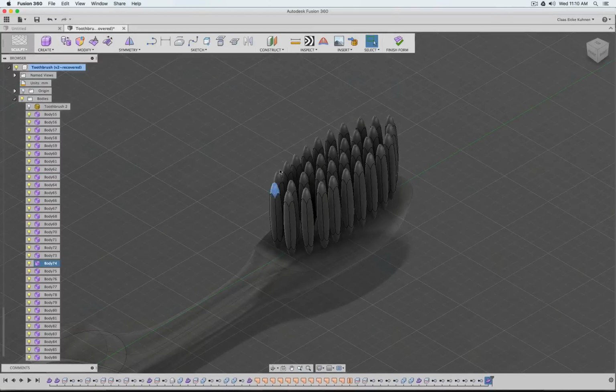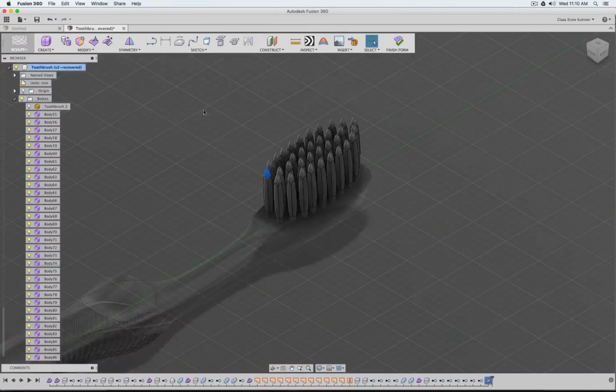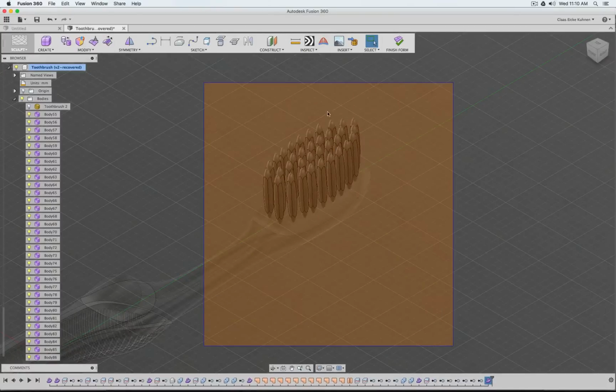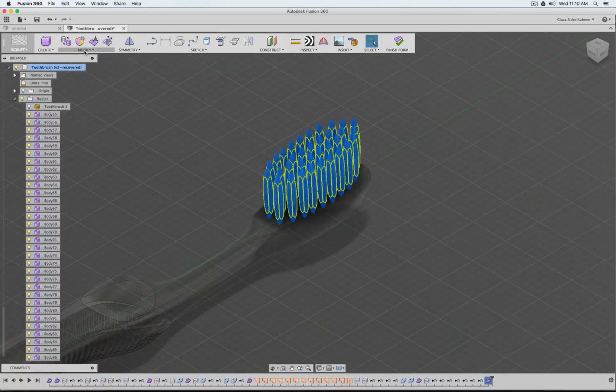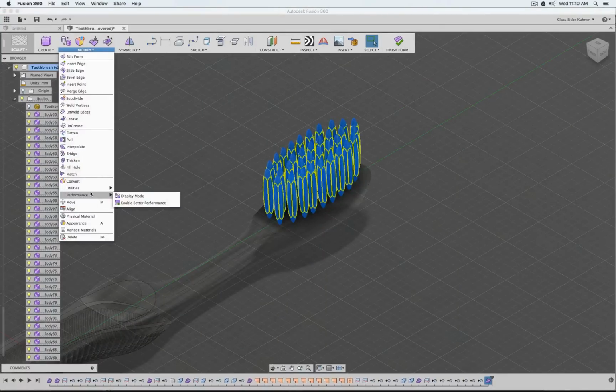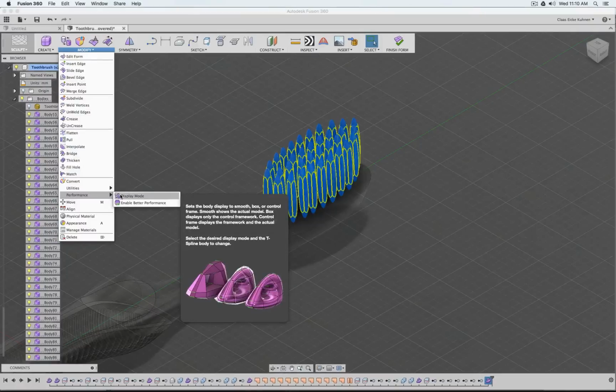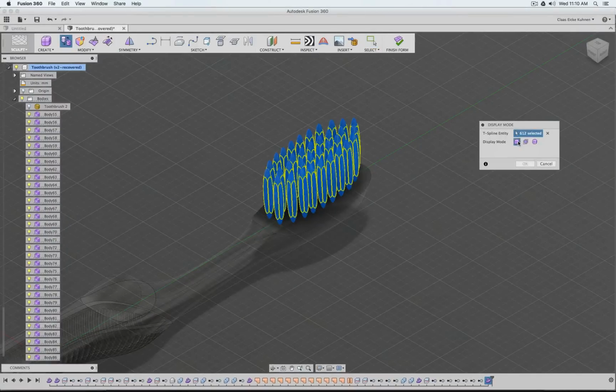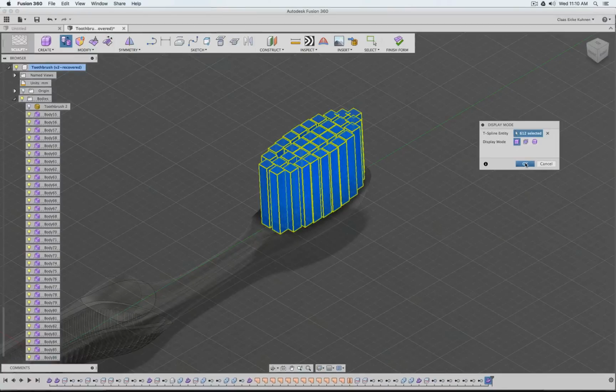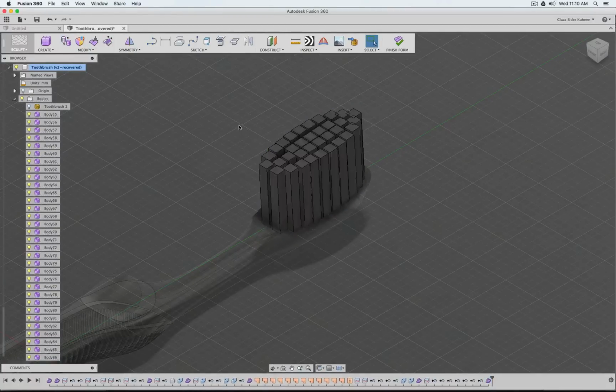But now I would like to cap actually all this tops, and I noticed that if we now go to the Crease command, Fusion can get very, very slow. So what I will do first is I will select these objects, go to Modify, Performance, Display Mode, and then set this to boxy look, which actually will make things a lot faster.